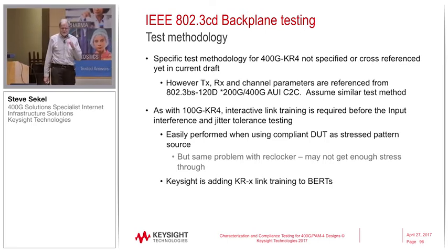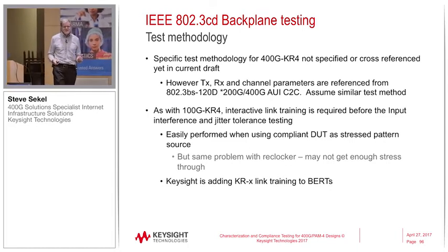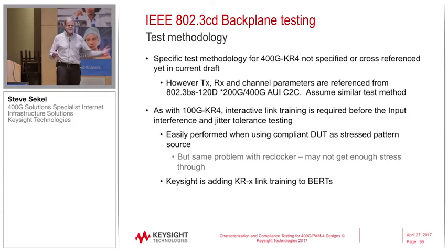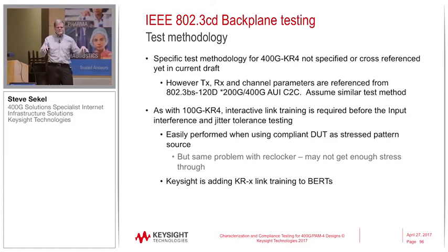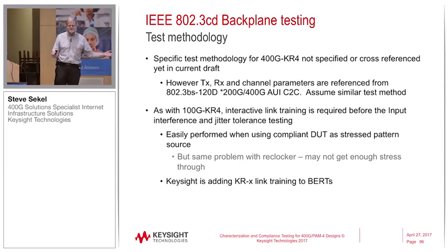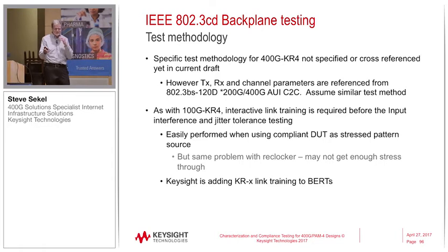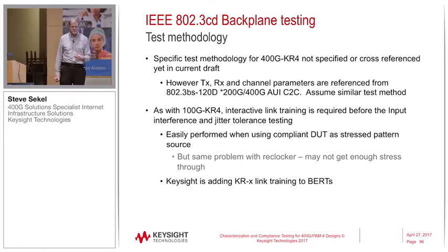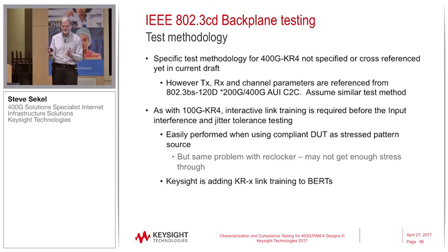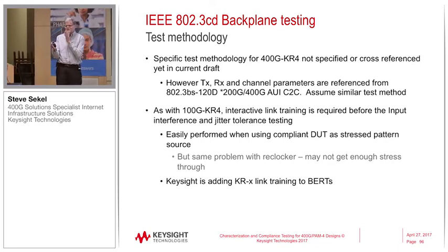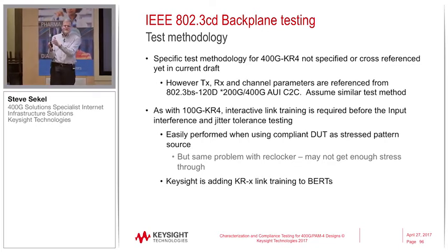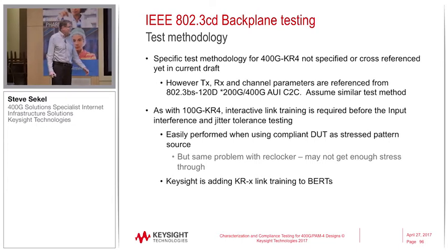The receiver does some auto optimization with its DFE and possibly CTLE gain as well, but typically the transmitter in a true chip-to-chip application does not vary. That's all hardwired because they know what the channel losses are within the range that they can tune the receiver, and that's just programmed at power-up. But when we deal with backplanes, that's a different situation, because the user could be plugging the daughter card or the second card into slot 1 or slot 13, and obviously every slot along the way is going to change the channel quite a bit.